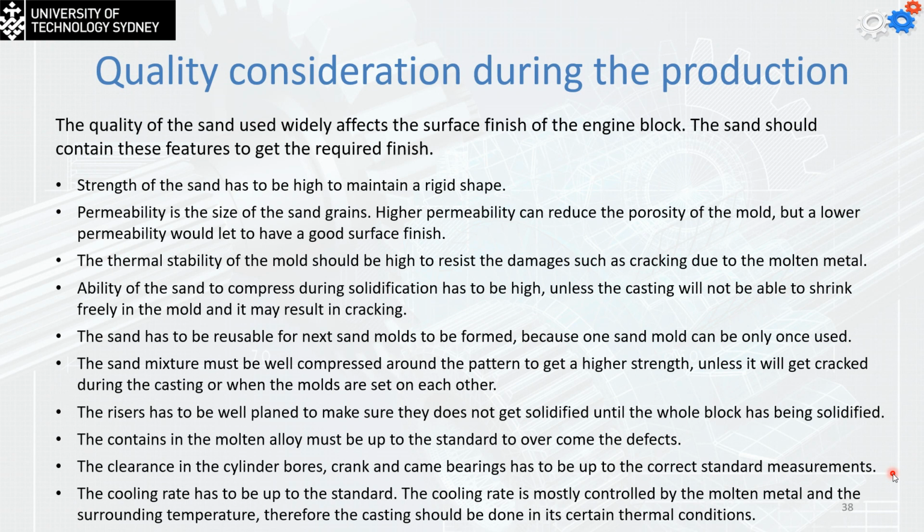The ability of the sand to compress during solidification has to be high, otherwise the casting will not be able to shrink freely in the mold and may crack. The sand has to be reusable for the next sand molding to be formed, because one sand mold can only be used once.